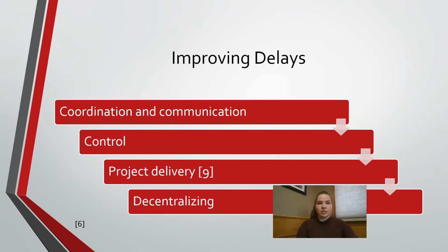RFIs can be more efficient if a system is implemented to organize the requests for information. Limit one issue per RFI to keep it simple and allow subcontractors and consultants to voice their questions. Organizing a number system to record RFIs is also important in the project-wide register to coordinate the delivery of information. Overall, waiting for RFIs can be made more efficient by enforcing an organizational system that streamlines the flow of information.